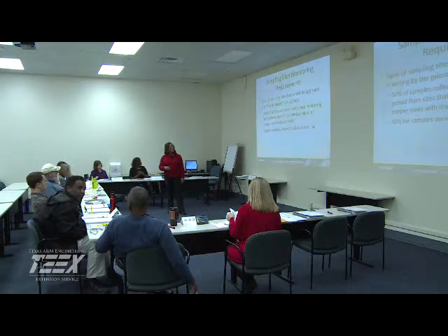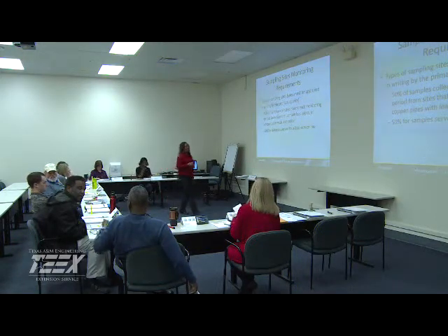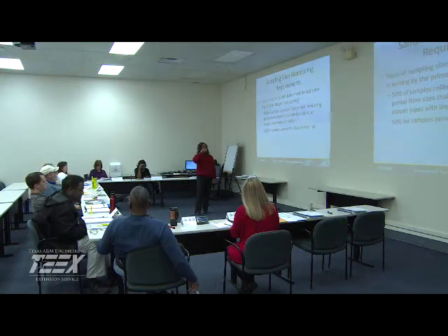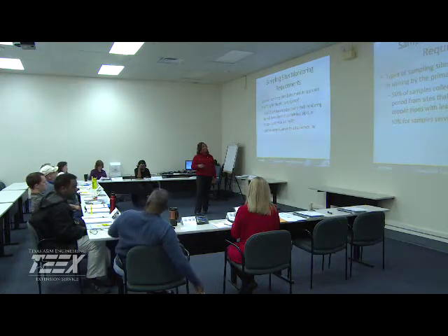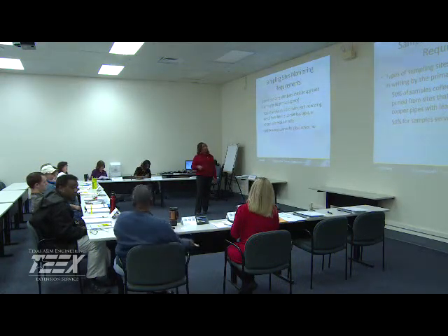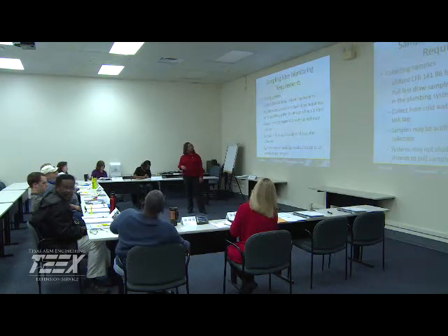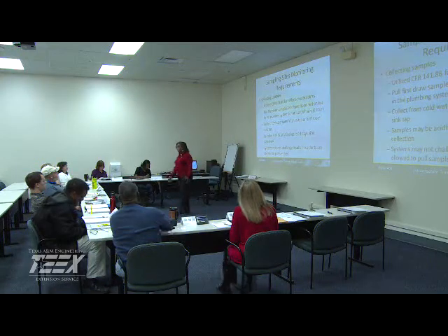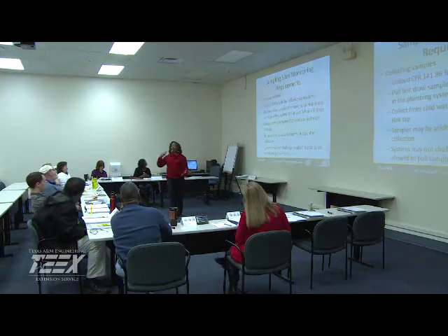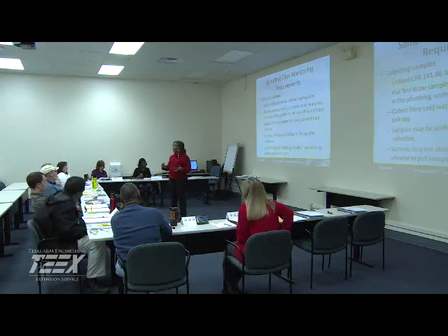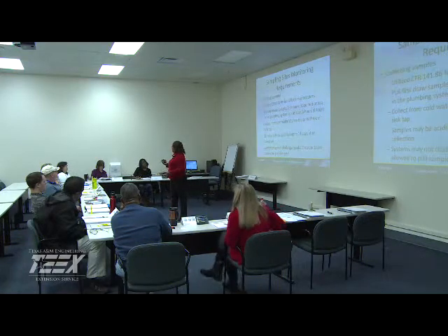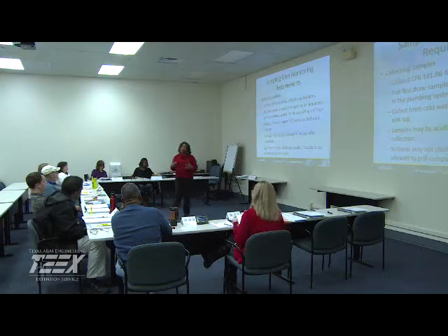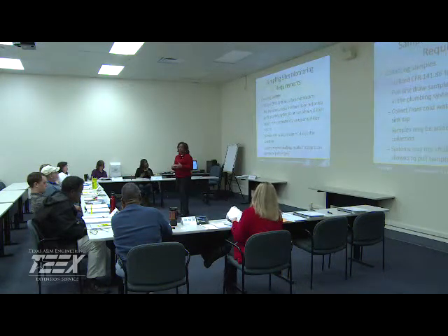50% of your samples collected during each monitoring period must be from sites that contain lead pipes or copper pipes, and 50% served by a lead service line. Now, collecting the samples, you have to use an approved method. If you don't have people trained to collect these samples, the rule does give some leeway for homeowners or residents to collect the samples.